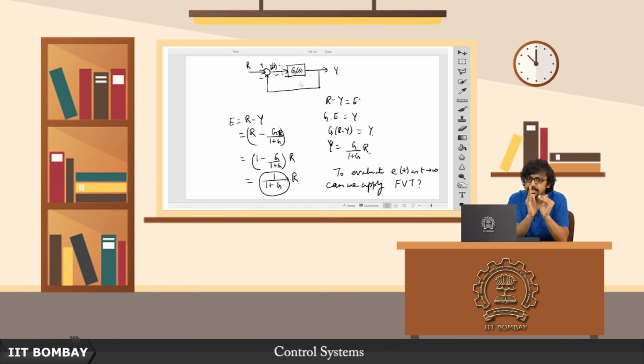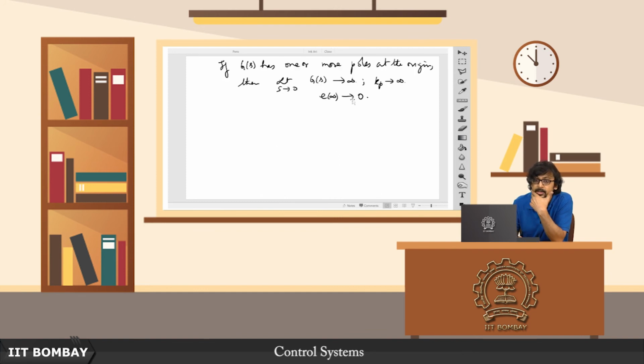So even if the instantaneous error signal is 0, but if there is an integrator present in the plant itself, then because of the non-zero error in the past, the signal which is coming out of this plant will not go to 0 immediately as soon as this E goes to 0, and therefore it will not let this signal fall. And so an integral action helps in maintaining zero steady state error.